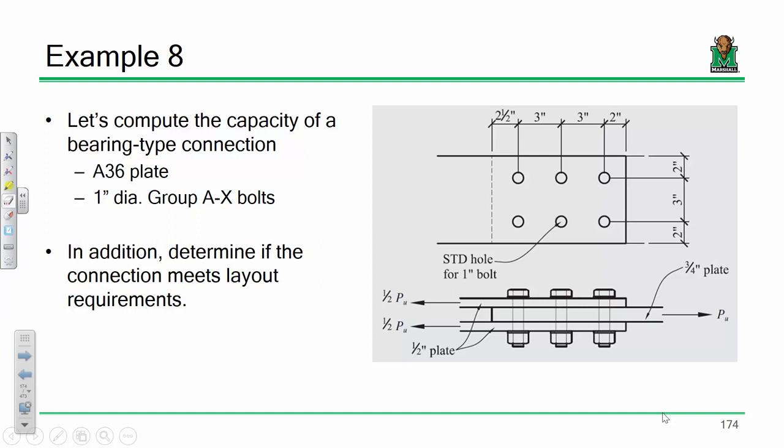You get a number, I don't remember what it was, but it was pretty high. It was something like 80 kips. 80.1. I can't believe I remember that. So that's 80.1 kips per bolt times the total number of bolts in the connection. That's 6 bolts. Bam, there's your bolt shear capacity. That's pretty simple. So something like 480.6 kips.